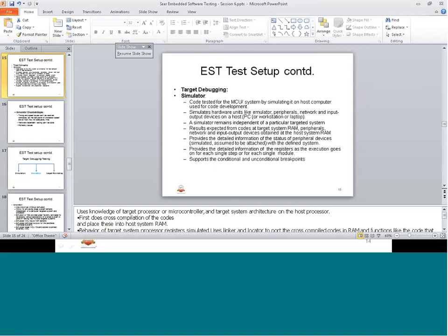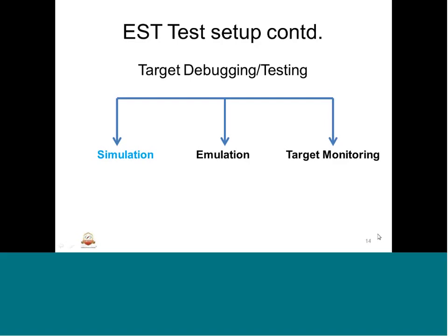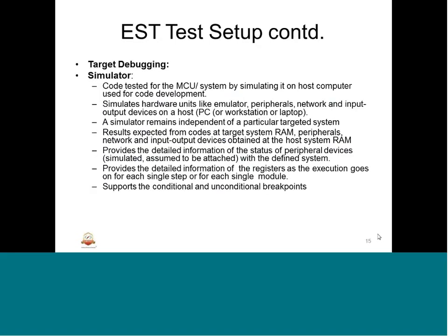So the embedded system target can be tested with the help of a simulator. In simulation, what it does basically is it uses the knowledge of the target processor or the microcontroller and target system architecture at the host side.